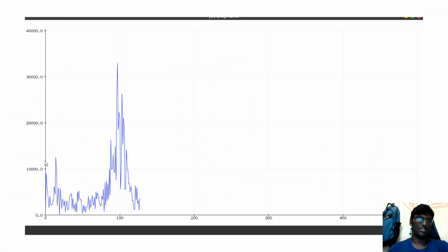This is the magnitude spectrum. As you can see, there are two peaks, this and this. The lower peak corresponds to the respiration rate and the higher peak corresponds to the heartbeat, because we know that the heartbeat has a higher normal frequency than the respiration rate. To find this frequency and deal with interference, we isolate this part, from the normal band of respiration, from indices 2 to 25.